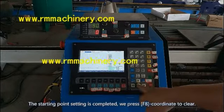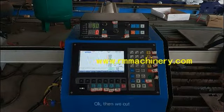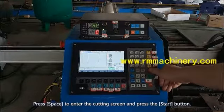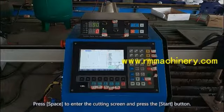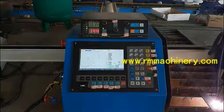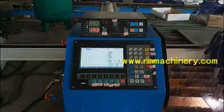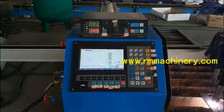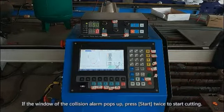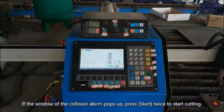The starting point setting is completed. We press F8 coordinate to clear. OK, then we cut. Press space to enter the cutting screen and press the Start button. If the window of the collision alarm pops up, press Start twice to start cutting.